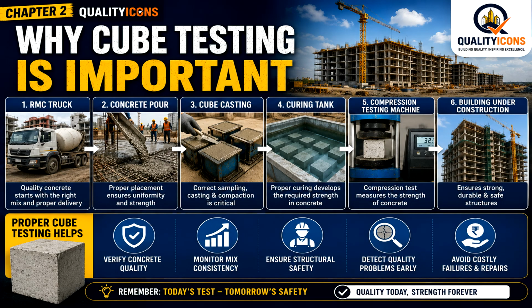So coming to the point, why is cube testing important? Concrete cube testing is one of the most important quality control activities in construction. It verifies whether the supplied concrete has achieved the required compressive strength. Remember it. Proper cube testing helps us verify concrete quality, monitor mix consistency, ensure structural safety and integrity, detect quality issues at an early stage, and avoid expensive repair or structural failures. Remember, strong structures begin with reliable concrete testing.